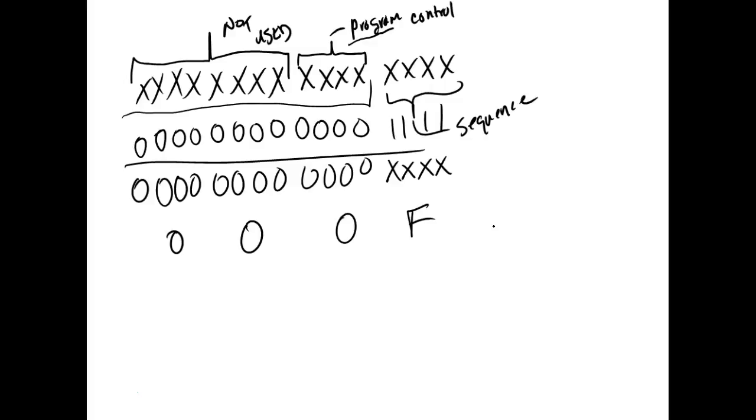I'm using those switches. So if I wanted all of them to come through, I would use F, F, F, F. If I wanted to use these ports up here for something else, like on the 504, you've got a 16-bit output module, right? You understand that? You don't want to clear out those outputs if they're being used by another program. So we might go F, F, 0, F. What this would do is let these other output ports stay the same, with whatever the last program set them to, and then these right here would actually update.